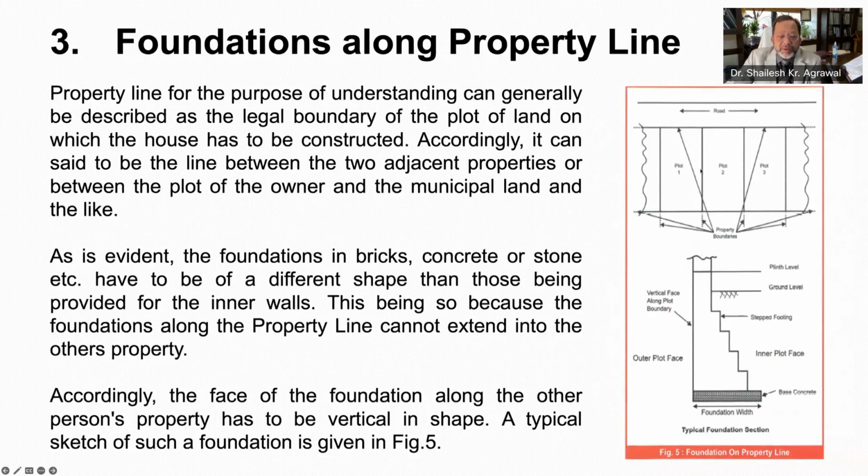Property lines are nothing but the legal boundary of your plot where the house is being constructed. Therefore, foundations in bricks, concrete or stone have to be of different shape at the property line than of inner walls. As you can see in the bottom right hand side picture, the foundation along the person's property line has to be vertical in shape instead of step.